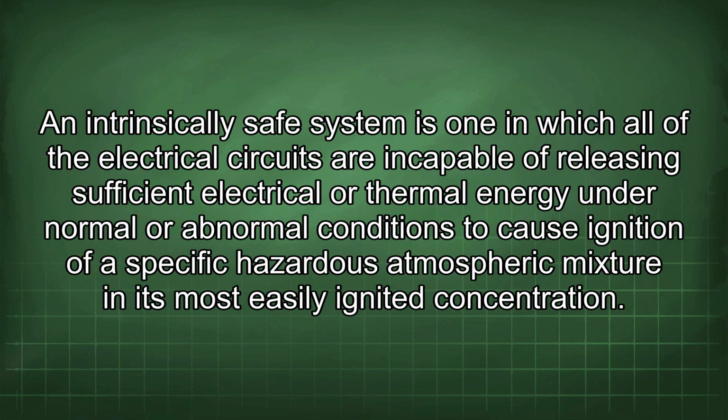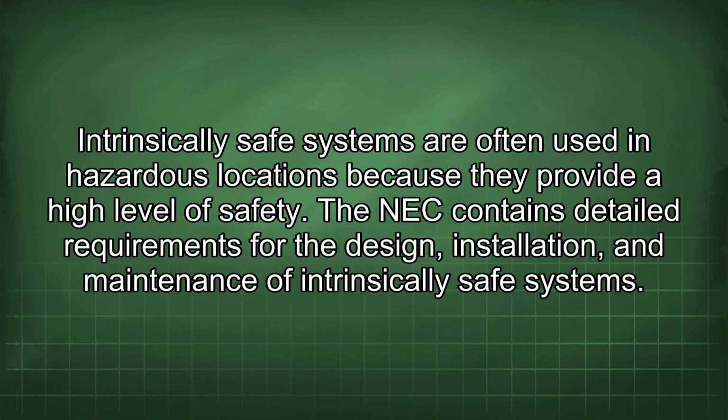An intrinsically safe system is one in which all of the electrical circuits are incapable of releasing sufficient electrical or thermal energy under normal or abnormal conditions to cause ignition of a specific hazardous atmospheric mixture in its most easily ignited concentration. Intrinsically safe systems are often used in hazardous locations because they provide a high level of safety. The NEC contains detailed requirements for the design, installation, and maintenance of intrinsically safe systems.